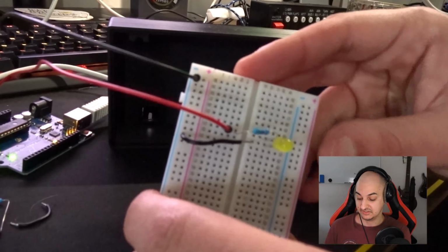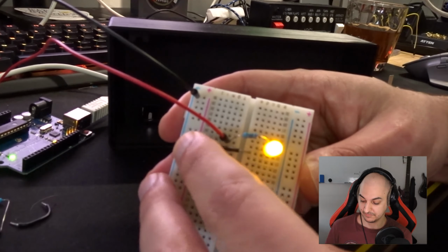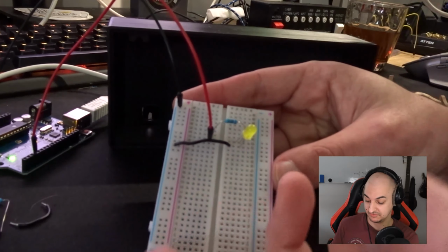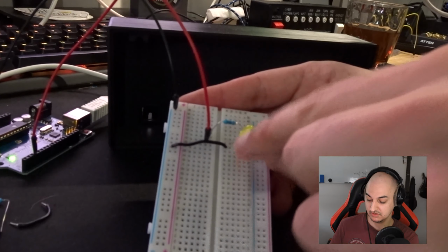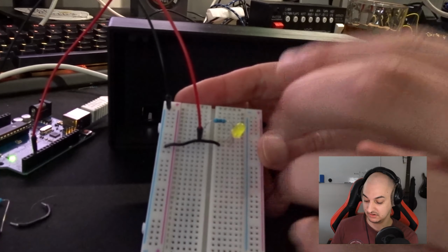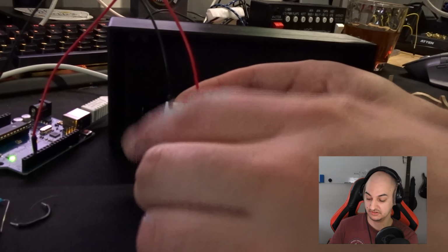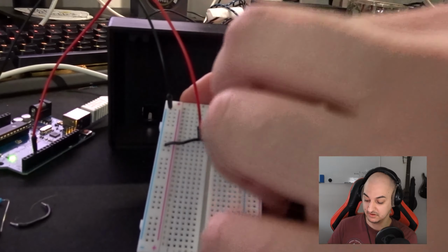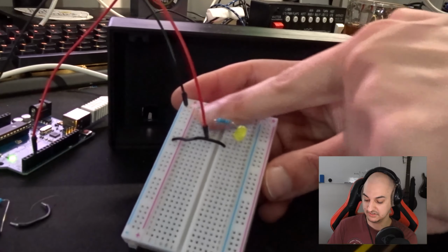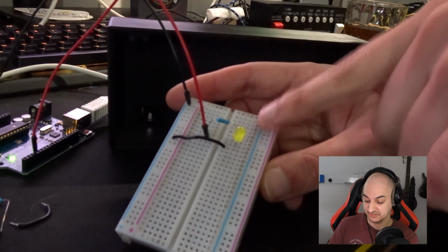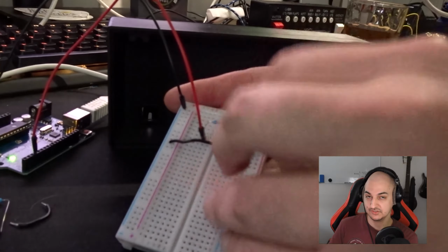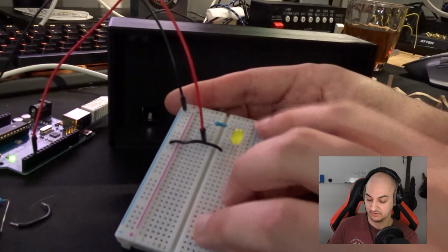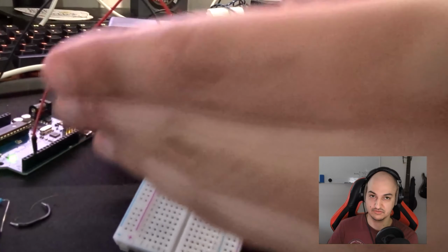Okay, I hope you're able to see how I wire this up. So we got our ground line, which goes to a common ground line, as we are able to tell. So the cathode side, so the smaller leg, goes to the ground side, and the power, which comes from a digital pin or an analog pin for that matter, goes to this row. Then it goes through the resistor to make sure that the LED survives, and then from there on out it can pass through the LED to the ground.